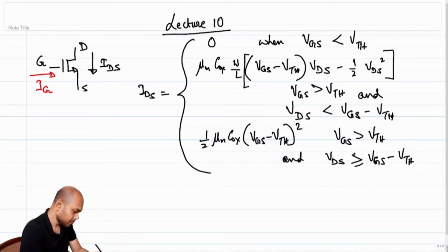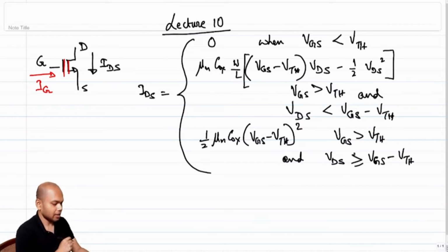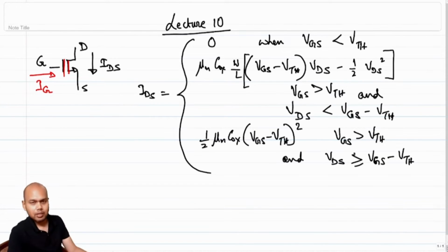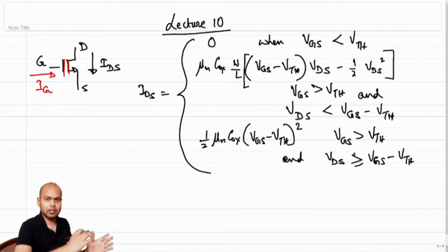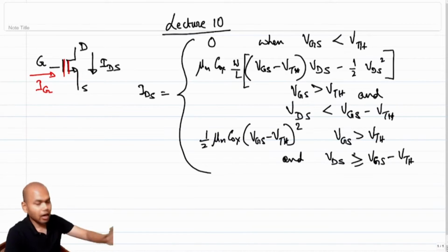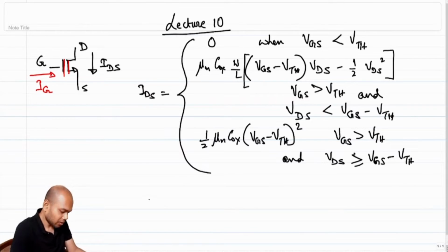So these parallel lines in a MOSFET symbol essentially symbolize the fact that there is a capacitance between the gate terminal and the channel, which is the other side of the capacitance. So naturally the DC current IG is always equal to 0 regardless of any other condition, right? So then IG is equal to 0 always at DC.